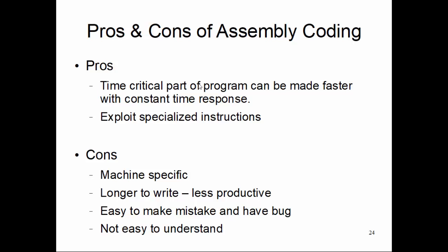Also do very systematic, step by step programming. Otherwise, if your program has a bug and you did not program it systematically and test it after almost every code change, then your debugging would be very hard. Finding a bug in an assembly program is very challenging.